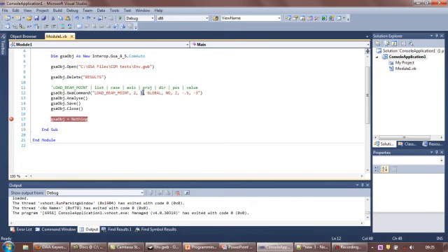element 2 belonging to load case 1 along the global axis, and not projected, along the z direction, with the magnitude at 0.5, which is at 50% of the beam length, and the magnitude is -3, which is 3 newtons, I think 3 kilonewtons, in the minus z direction. Analyze the model by calling the analyze command, save it and close it, and then set the GSA object to null before exiting the program.